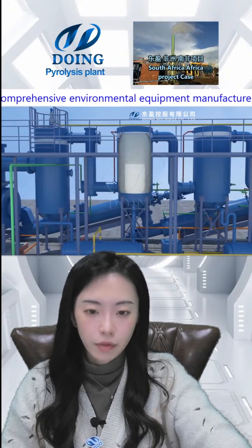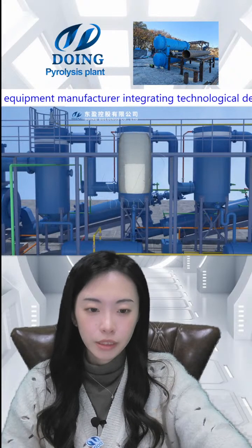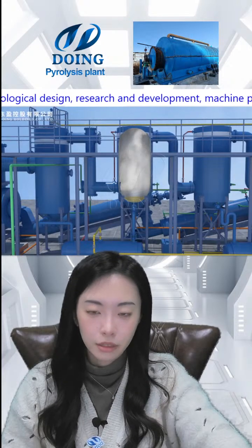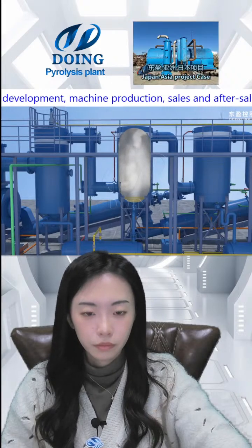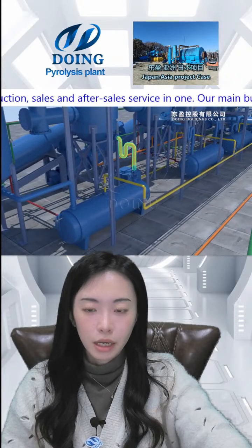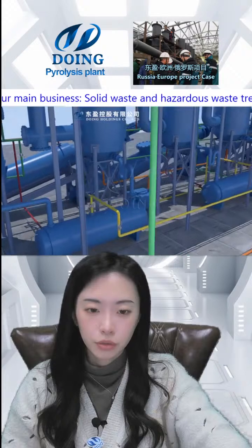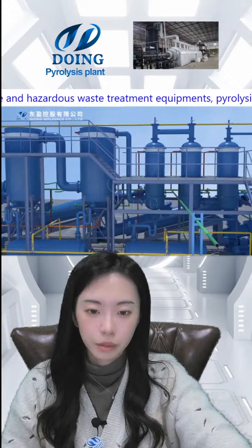And then this is a buffer condensation tank. We have 3 tanks to further precipitate impurities and provide the buffer effect. Outside is the water jacket, which condenses the gas into oil. This is a U-tube design. The oil comes through the U-tube to this storage tank. The U-tube balances the pressure to prevent oil gas from entering the oil tank during pumping.